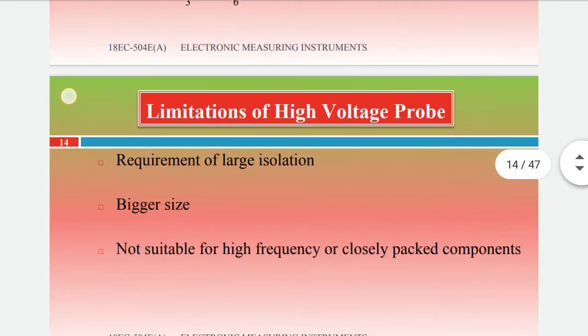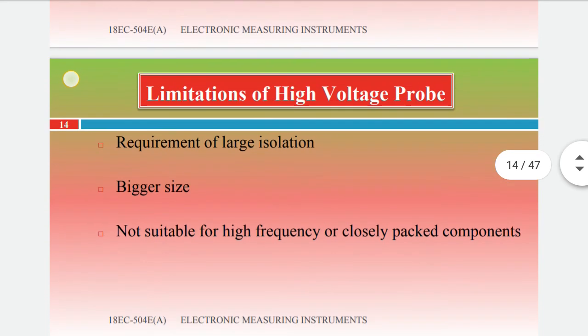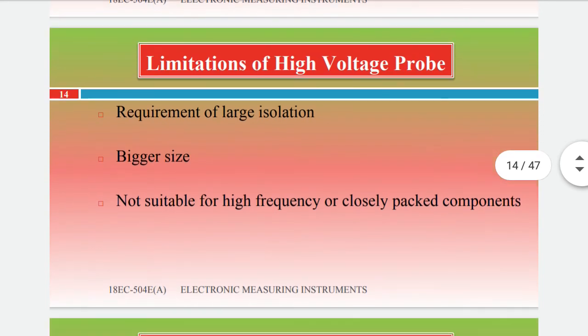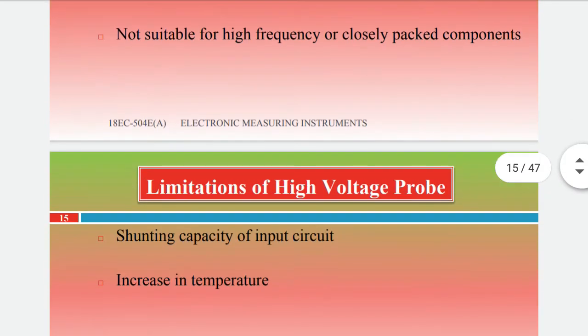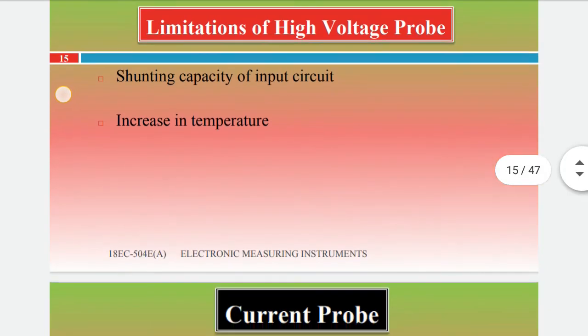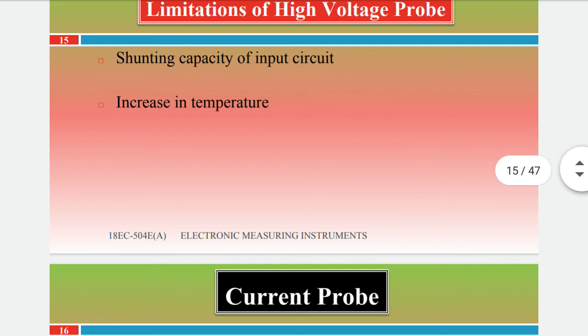Okay, now let us move on to the limitations of the high voltage probe. It requires large isolations and bigger size, which is not suitable for high frequency and closely packed components, and there is shunting capacity of input circuit and increase in temperature. These are all the limitations of the high voltage probe.